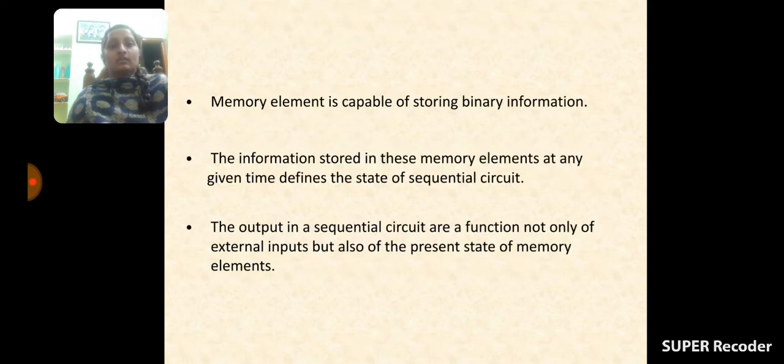See here in the slide, briefly explained. What is the use of the memory element here? It is capable of storing binary information, and the information stored in these memory elements at any given time defines the state of the sequential circuit. The previous stage output is stored in the memory element in the form of binary. It means sequential logic circuits also work with only binary, not octal, not hexadecimal, not decimal numbers.